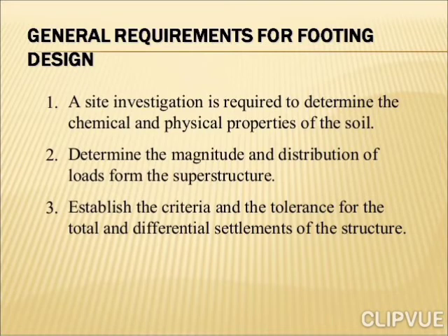General requirements for footing design. A site investigation is required to determine the chemical and physical properties of the soil. Determine the magnitude and distribution of loads from the superstructure. Establish the criteria and the tolerance for the total and differential settlements of the structure.